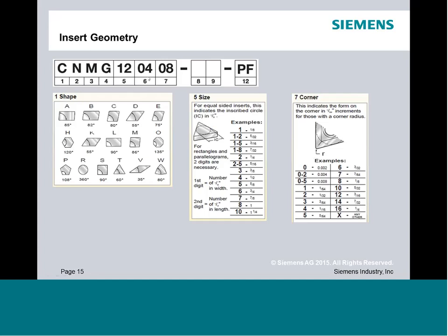From there, 6, I'm pretty sure, if memory serves me, is directly the thickness. 7, however, is another important one we want to look at, and that's your corner radius. So if this, again, was a 432, I would look for the 2 field, and that would tell me, oh, I got a 1/32 or an 031 radius on that physical tool. And then I can build it from there.